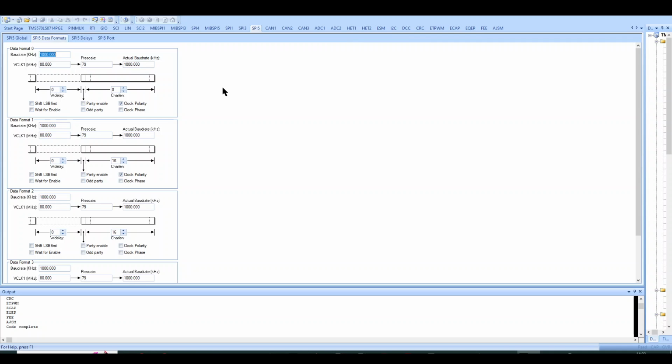So if you're then sending multiple bytes, you're going to end up in a situation where you've got an array of 16-bit words, and you need to set your array of 8-bit data into the lower 8 bits of each word. So it adds in a level of work for you to do.